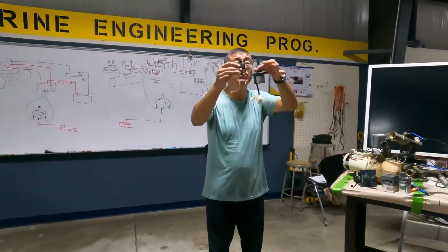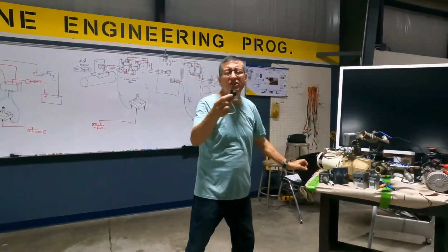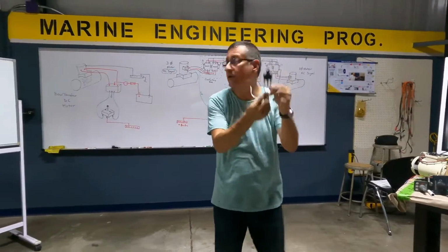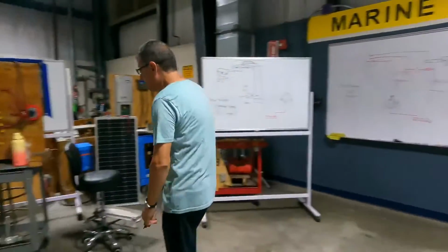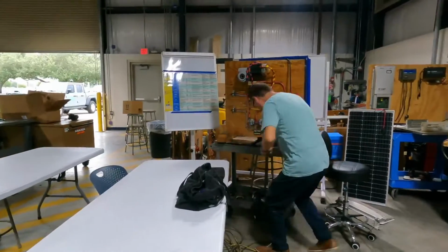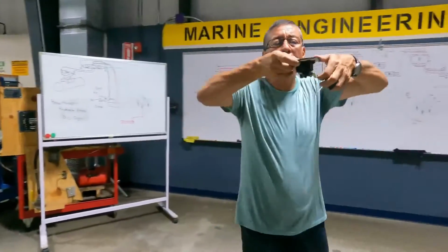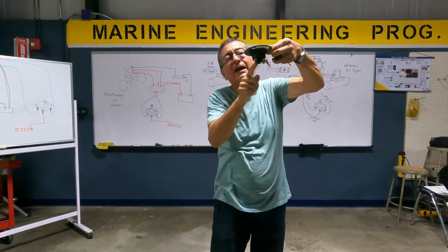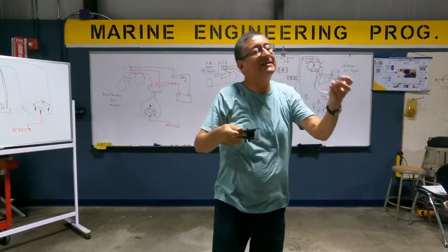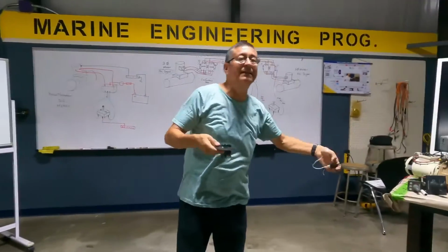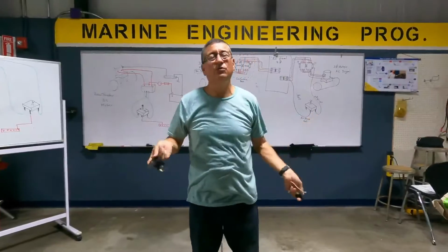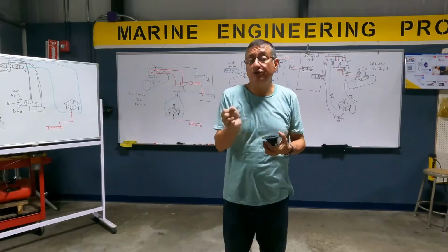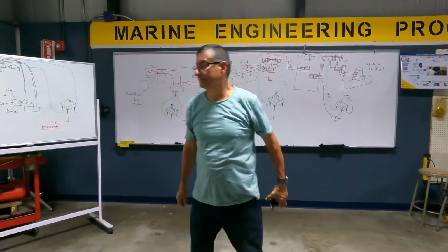Okay, we are going to use any of those joysticks. Mr. Lopez, instead of the joystick, can I use a couple of push buttons? Yes. This one can be replaced with 2 push buttons. You remember? 2 push buttons like this, one here and one here. You connect the middle one, common, and this is signal 1 and the other is signal 2. It's exactly the same. You can use the switch that you prefer: push button, toggle switch, or joystick. No difference.